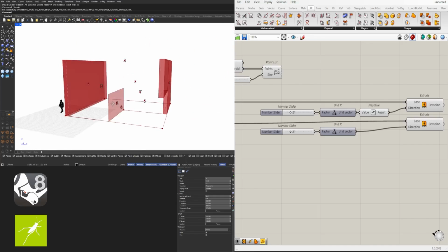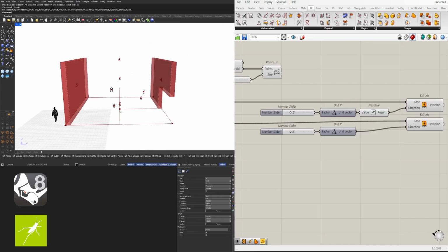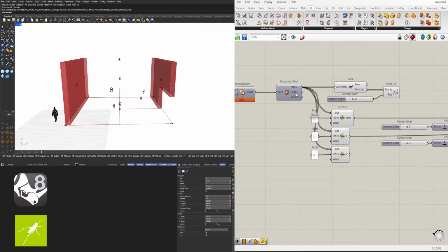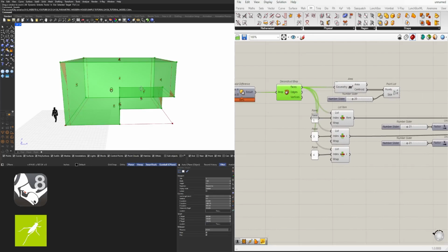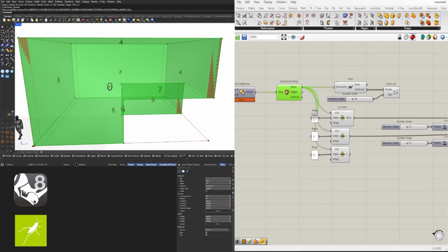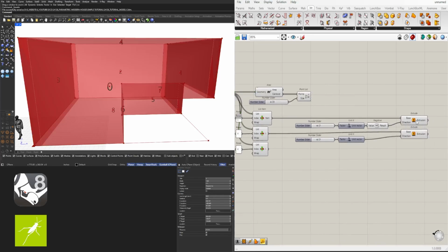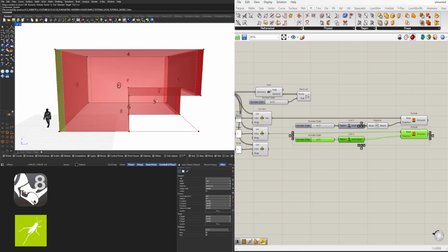Now 6 is going to be an interesting one because if we extrude it to the inside, then we'll have a gap here at the top, because if we extrude it to the inside, this one will extrude up. And so there's going to be like a missing portion. So we're actually doing this the same as 3. Going to be in the positive.